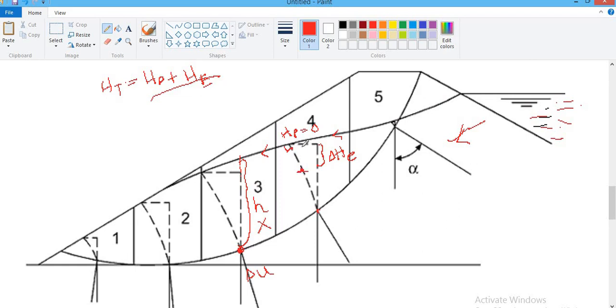Due to the water above that point, that creates a pressure. So this reduction of elevation head should be equal to the gain of pressure head, because ultimately pressure head plus elevation head should be at the same value.